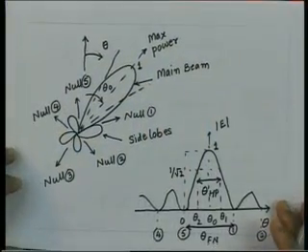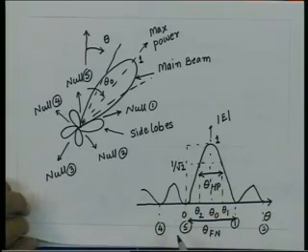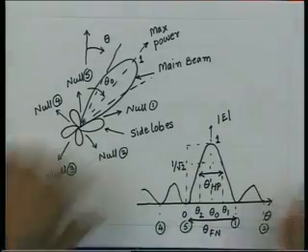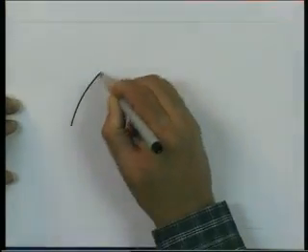Now, as we have done earlier, if I make an approximation to the radiation pattern as we defined here, and if I say that effectively the power is confined to the half power beam width, and I take two planes, and let us say side lobe levels are much smaller for this antenna. So, I have an antenna whose radiation pattern is typically like that.